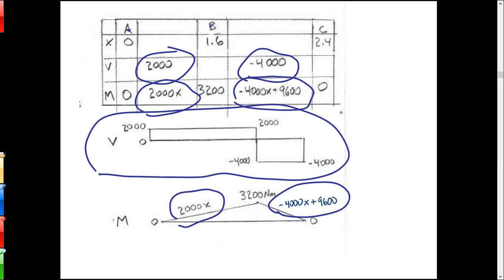When they built North Santiam Hall, we went in there and had a look at it. The joists for the floors are actually trusses. They look like that. Okay, however they put them together. But I was noticing that they got quite thin at the supports there. And I was talking to the engineer about it, and the engineer was saying, well, we ran our shear and moment diagrams, and the moments are quite low at the supports at either end, so we didn't bother beefing them up. Okay? Save a little money there.